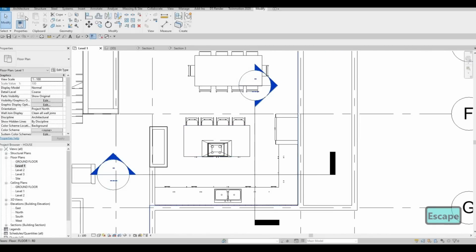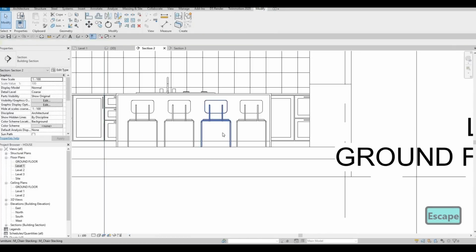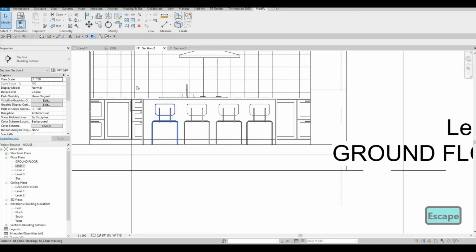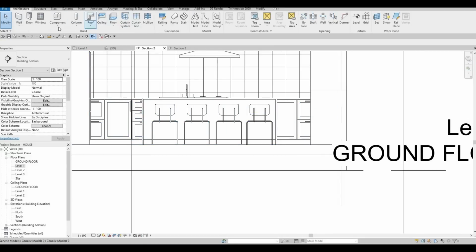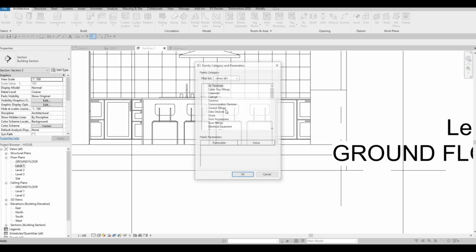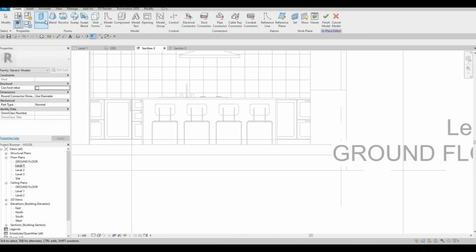Instead of right here, we can go back right here, flip this one, and move it on this side. So now I'm gonna do it again, but looking at this side. Generic model, and then here I'm gonna do a sweep again,